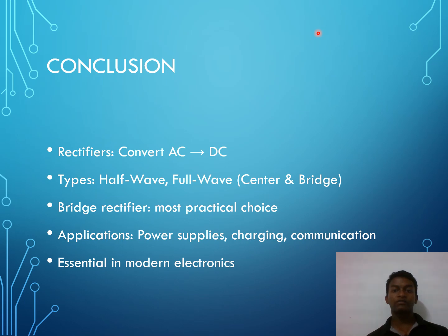The half wave rectifier converts the half cycle of AC into pulsating DC, while the full wave converts the full cycle into pulsating DC. Our selection between half wave and full wave rectifier should be based upon the requirements. If we require a low cost device and can compromise on efficiency, then use half wave. But if you are working on some specific circuit design which requires highly efficient conversion of AC to DC, then use full wave, keeping in mind its circuit complexity and high cost.